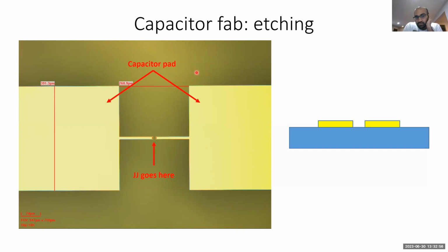So you can do pretty aggressive cleaning after this stage and before you start your junction fab. Typically what we do for our tantalum processes is we just do a piranha clean. A piranha clean is really good at removing all organic residues. So if we're worried that there's some photoresist left over or some hydrocarbons on any surfaces, the piranha clean will take care of it.